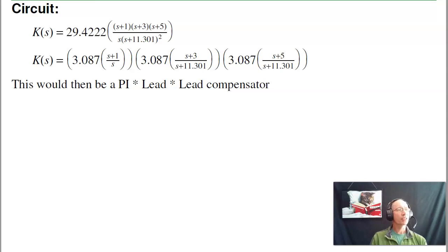So that's lecture number 26, meeting design specs. Basically, you add poles and zeros. Add a pole at s equals 0 to make it type 1 if it's not already type 1. Start canceling poles with zeros until you're too fast, and then clean it up. If I added 3 zeros, make sure you add 3 poles. One goes at the origin, the other 2 go wherever it takes to set the angles right to put your design point, in this case minus 2 plus j3, on the root locus. Then pick a gain K to make the gain 1 at that point. Lecture number 26, meeting design specs with root locus.